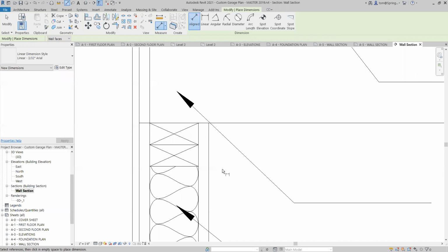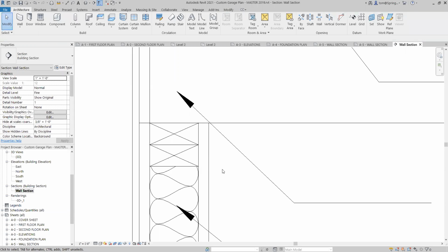This one would be probably 16 feet, or it might be 20 feet or something else. But that's a long board. But we're just looking at the end of it. That's the profile. It's 2x4. Now, the reason a 2x4 is not really a 2x4 is because they used to be. Years ago, a 2x4 used to be exactly 2 inches by 4 inches. And then as time went by, the lumber industry got better and better at dressing lumber to exact sizes. However, when they did that, they actually decreased the size. So this is the reality of it. Now, a 2x4 is actually now 1.5 by 3.5. That's actually how that works. And everybody knows that who actually builds anything, and that's actually how you use it.